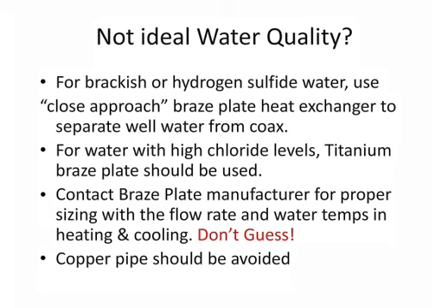So you need to reach out and say, this is my flow rate, here's what my entering water temperature is, and I need a good 10 degrees difference. What size does that need to be? And by the way, here's the fluids I'm running through it, and here's the test results. Have them help you. Remember, they want you to buy their product, so they are more than happy to help. Don't guess at it, folks.